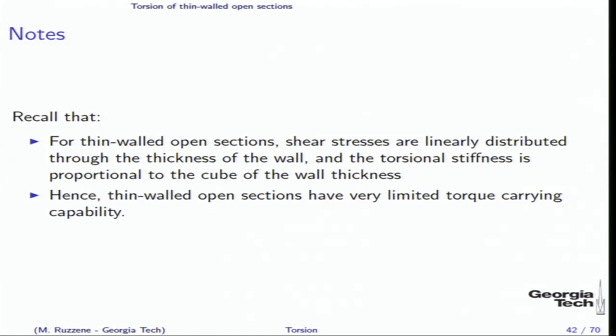So it is warping. Whereas if you had a closed circular loop like this, it becomes a thin walled section, but it's closed, so there won't be any warping. So it becomes stronger in torsion. The torsional stiffness will be higher as compared to an open section. So if you see aircraft wings, they are always a closed section to make them stronger in torsion. If they were open sections, they would just not work in torsion, right? The allowable stresses would be very low.